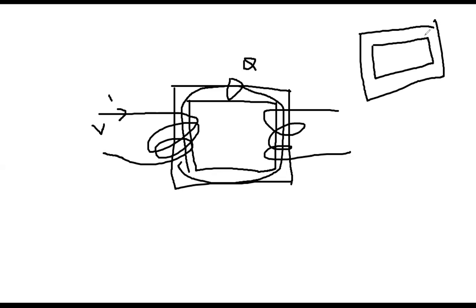what happens when this flux flows inside the core material, because these are magnetic material, and you see this flux is flowing, so they create some sort of internal voltage and internal current, and those are circulating in nature. For example, one current is flowing here locally, other current is flowing here, some current is flowing here. Those are called the circulating current. That is the meaning of the word eddy. Eddy means circulating current.